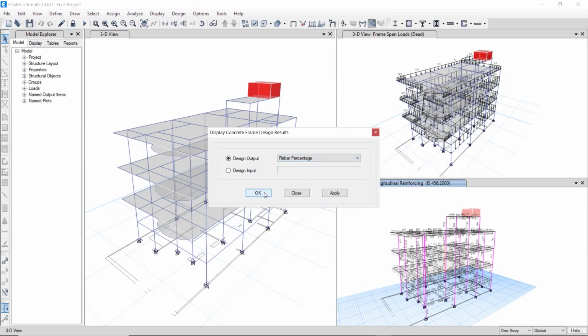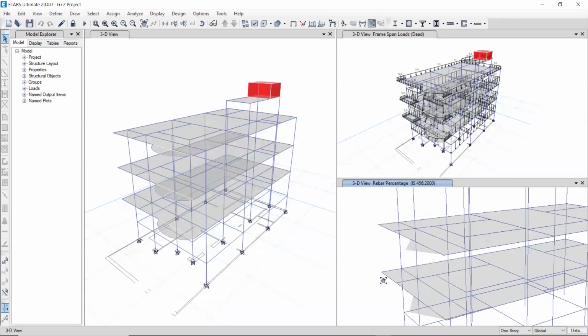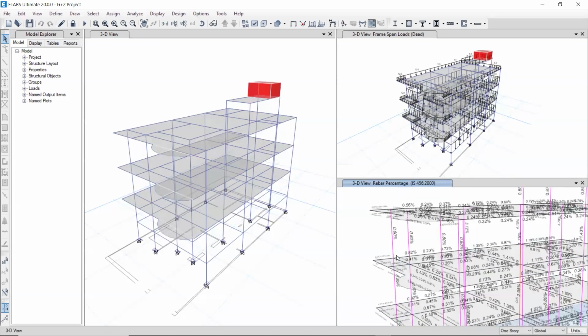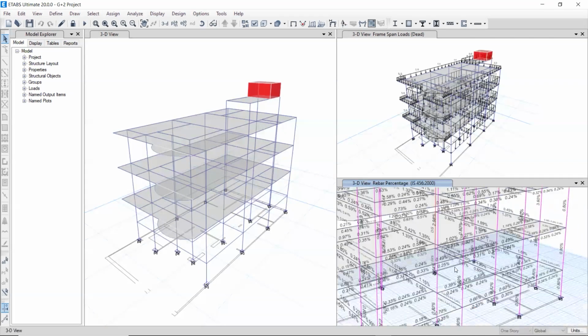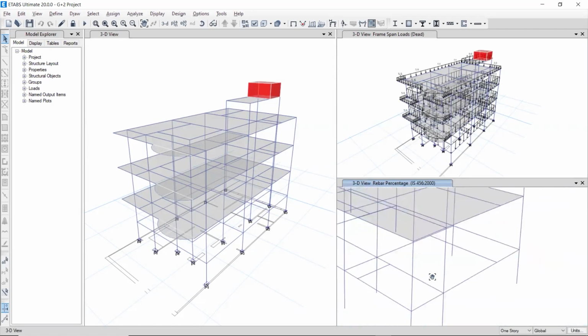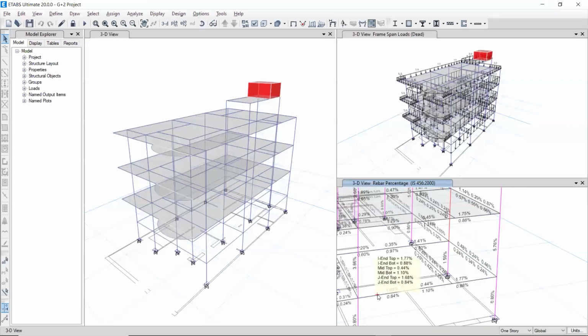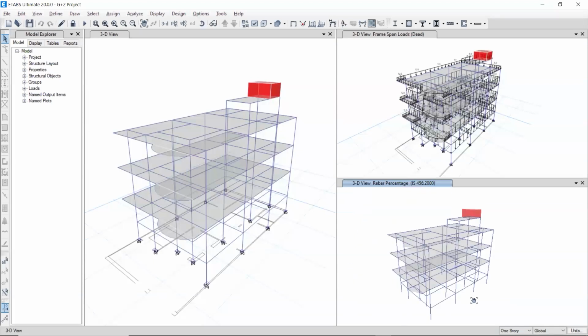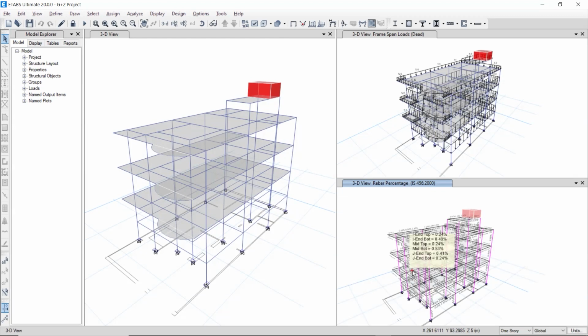You can go through it, and here you can see we receive the minimum reinforcement of 0.8% in columns. Even the beams are receiving less reinforcement. Here you can see the larger beam. It is getting 1.68% at the supports, and at the bottom center part of it, it is getting 1.10%. With the help of these results, we can actually go on to design the RCC sheets for our client. So this is how we get the results from it.